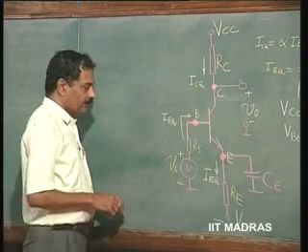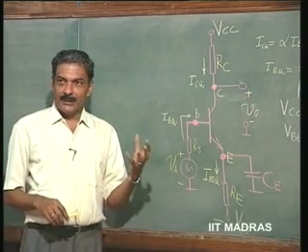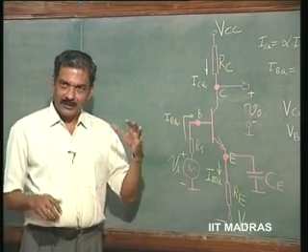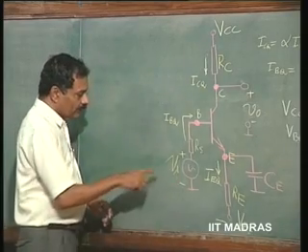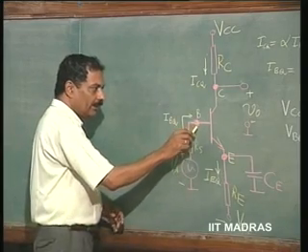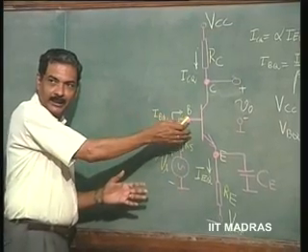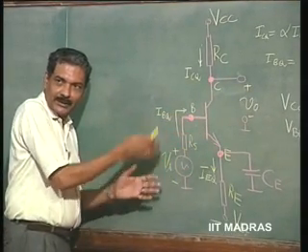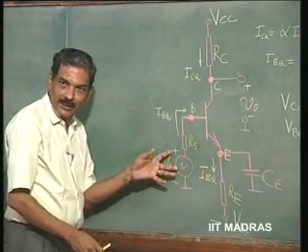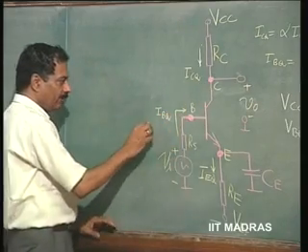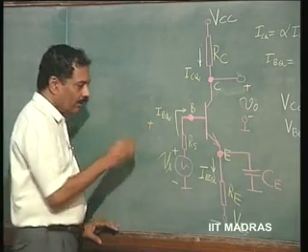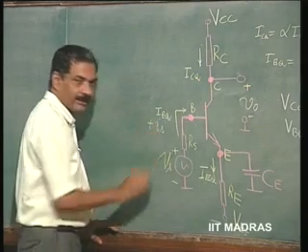The small letters with capital suffix indicate the instantaneous value of the signal at any time, including DC as well as AC. So, this is the variation Vs. For this variation, this is going to increment the base emitter voltage. So, base current is going to increase, because emitter current increases, base current also increases. This polarity, the base current is increasing in this direction. That means IBQ plus delta IS, that is what we have been using, or we can indicate it as only signal IS.